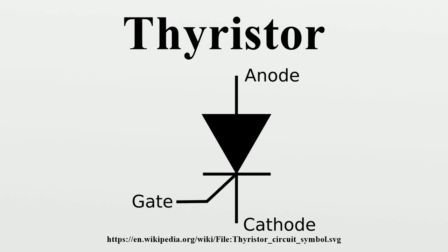Because thyristors can control a relatively large amount of power and voltage with a small device, they find wide application in control of electric power, ranging from light dimmers and electric motor speed control to high-voltage direct current power transmission. Thyristors may be used in power switching circuits, relay replacement circuits, inverter circuits, oscillator circuits, level detector circuits, chopper circuits, light dimming circuits, low-cost timer circuits, logic circuits, speed control circuits, phase control circuits, etc.